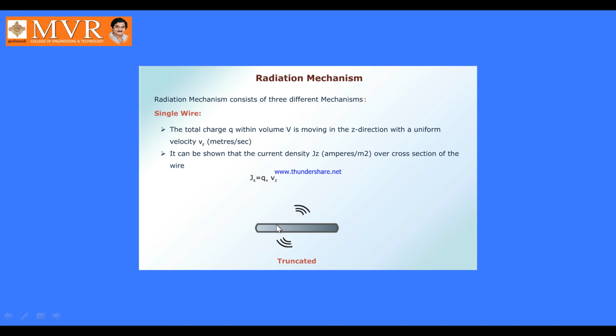In the above antenna scenario, what I said was two dipoles which are center fed. The center feed is excited with the voltage source, right? But in a single wire antenna, how does the radiation take place? That means how is the wire excited? If a charge is stationary, that means the device is like this, no current is developed, so no radiation is observed.